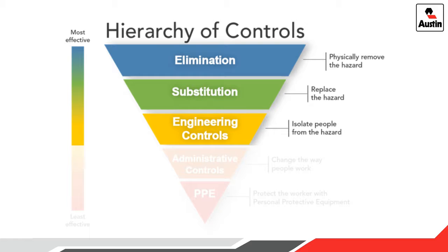Engineering controls isolate people from the hazard. For example, this could mean using lockout, tagout, blinds, blanks, or double block and bleed in a hazardous energy situation. A crew might build a work platform rather than purchase or replace and maintain fall arrest equipment. Enclosure and isolation creates a physical barrier between personnel and hazards, such as using remotely controlled equipment. Fume hoods can remove airborne contaminants as a means of engineering control. Can you think of other ways that we can engineer the hazard out of our work?